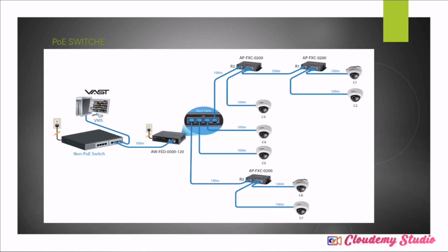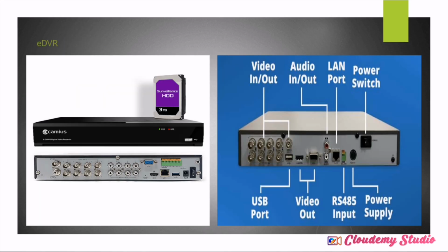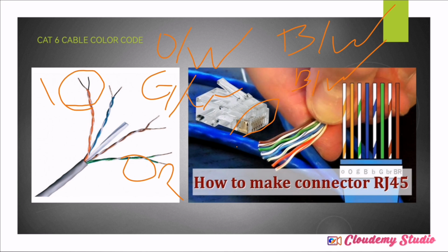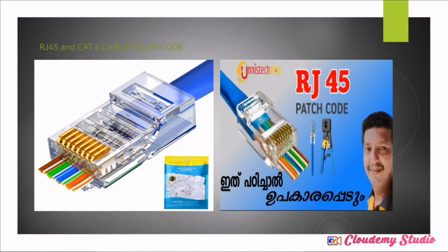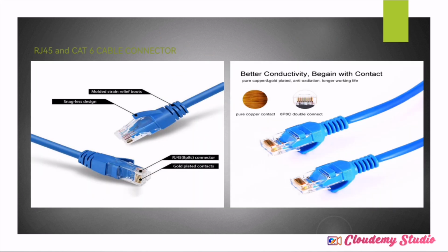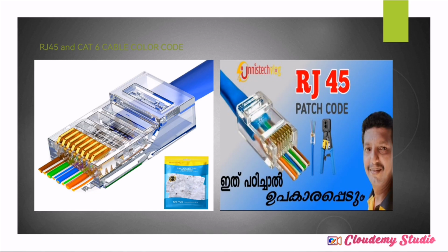Because if you don't crimp these terminals, if you don't push them down using the crimping tool, then they won't fit. So make sure that you crimp them using the crimping tool. It's not even difficult. I will show you guys. So this is the RJ45 and this is the network cable, but it's not complete unless you've done the crimping. You cut it here.